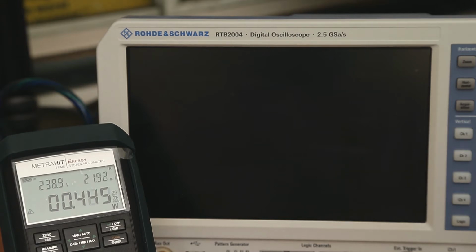Now I measured my Rigol, because I've got 3 scopes. The Rigol DS2000 series standby takes between 0.48 and 2.74 watts. It pulses because of the front light, and pulses at full brightness, goes up to about 2.7 watts. The Keysight, as I said, is about 6.4 watts, which is just bizarre, and this is running at about 0.43 of a watt, so it's very efficient when it's in standby. Not that I tend to leave it all the time powered up in standby, but at 0.4 of a watt one could quite easily and quite happily do that.